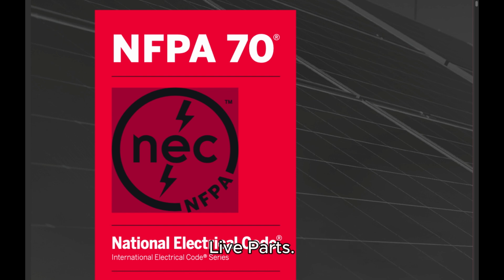110.27 Guarding of live parts. By any of the following means: 1. By location in a room, vault, or similar enclosure that is accessible only to qualified persons.